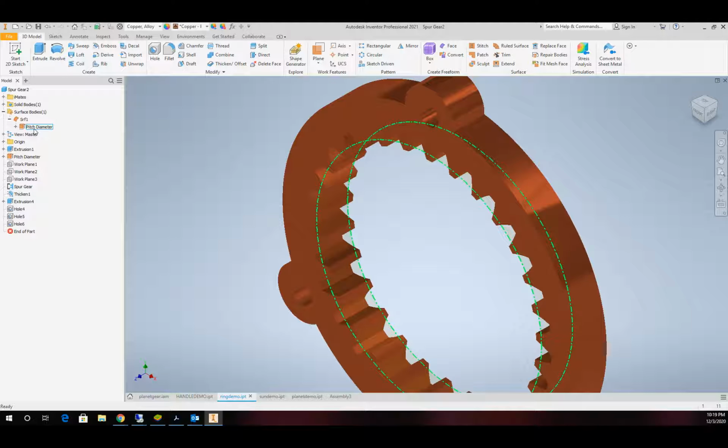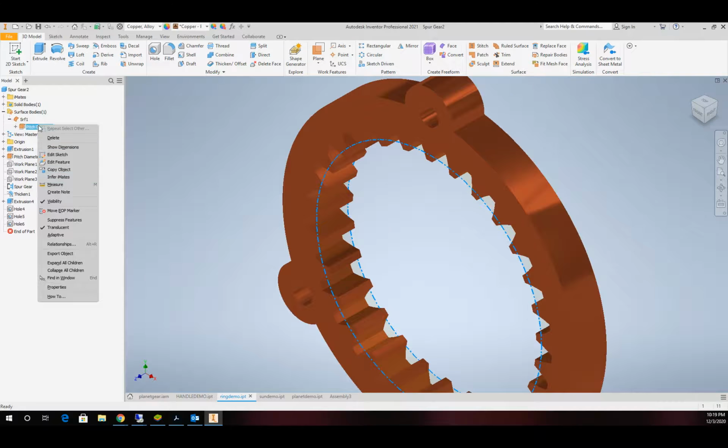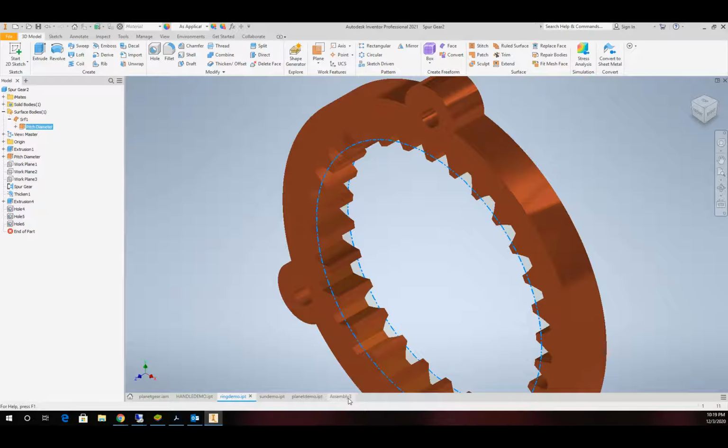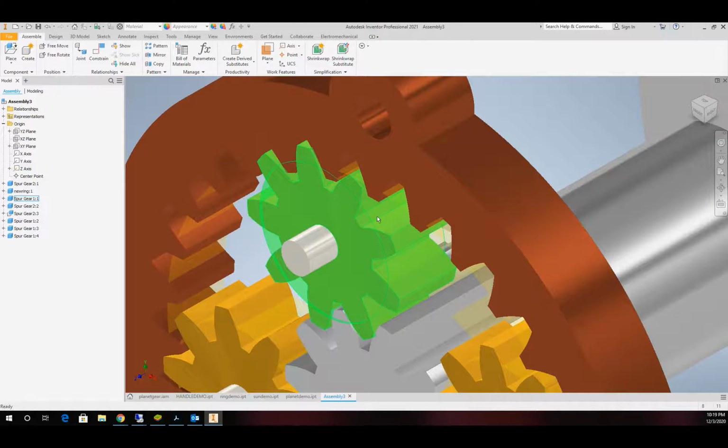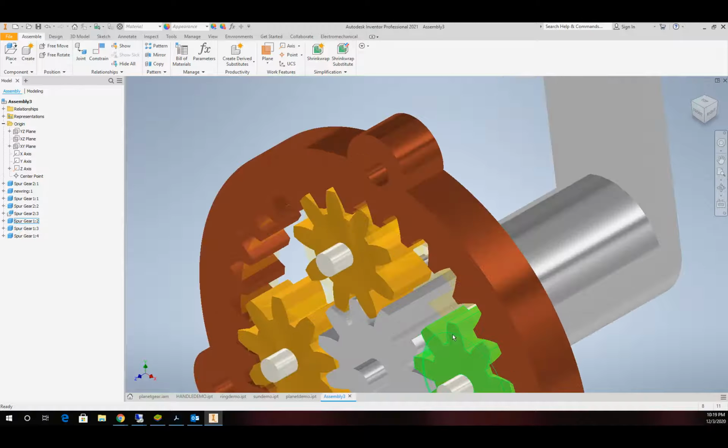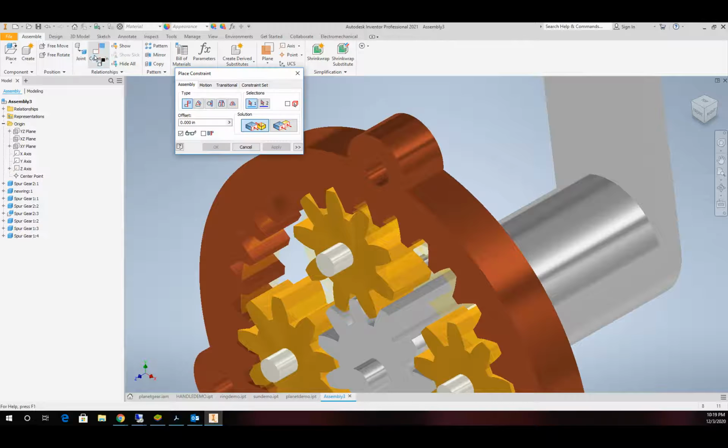And that's really what we need to do a lot of the functionality to make these gears work. So I've gone ahead and turned the visibility of that on all my parts so that they're available and easily used here. Okay, so our next constraints are going to be motion constraints rather than assembly.